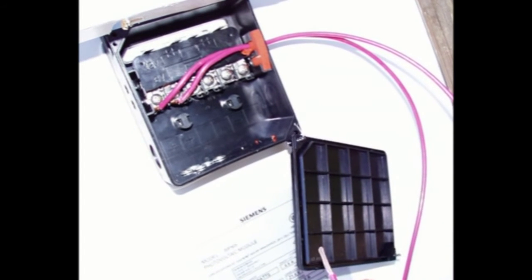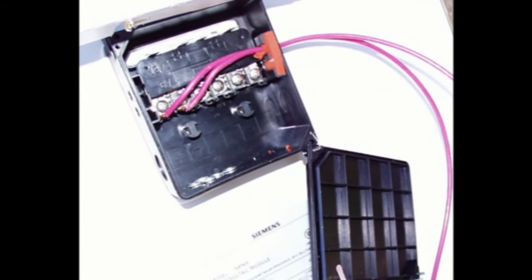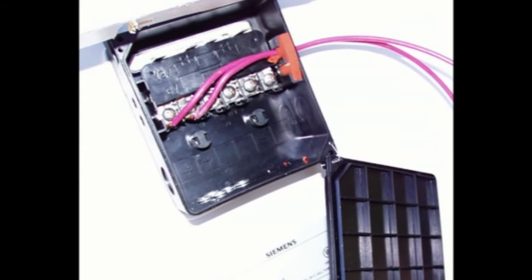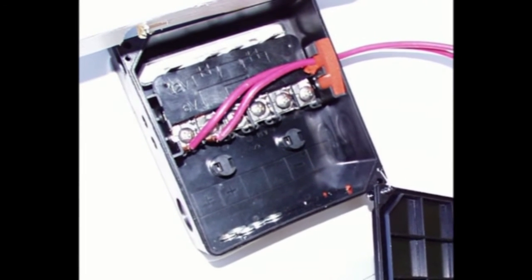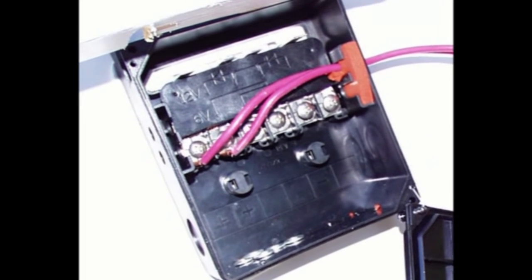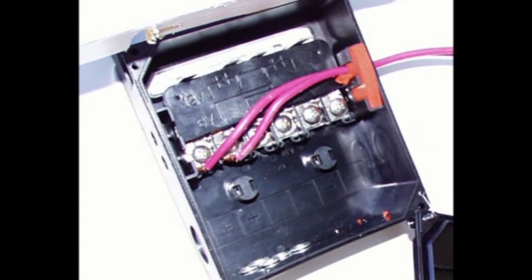Now let's look at our actual physical wiring connections on the solar panels themselves. Up until recently, all panels came with connection boxes on the rear like this. You can see that the wires connect under the screw heads. The panels will show which are the positive and negative screws. Some have jumpers for configuring them for 12 volts or 24 volts. Follow the diagram in the box to set it for your desired voltage.